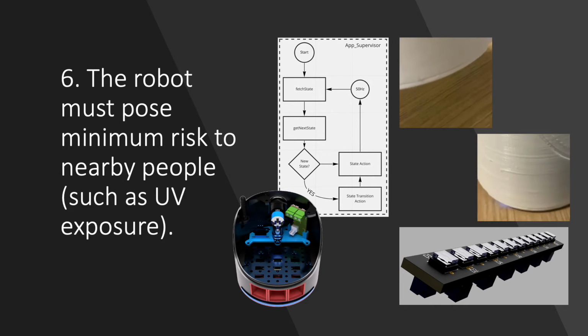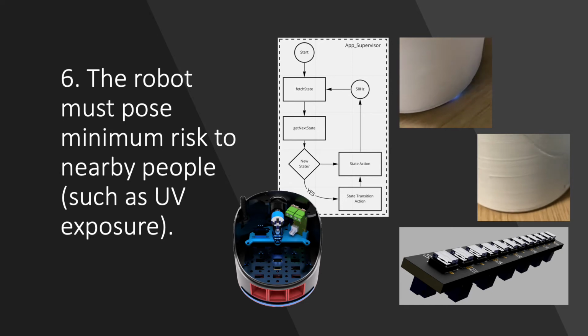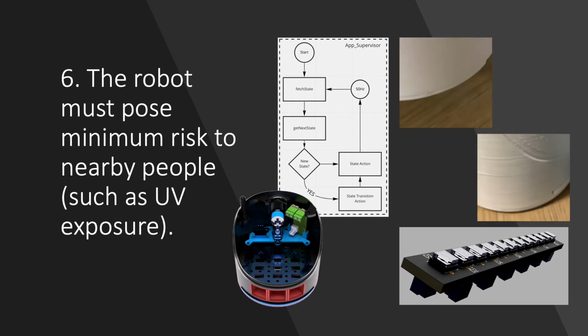Mechanically, the layout of the UV lights is designed to minimize UV leakage through the table reflections. The robot is elevated within 3 mm from table surfaces to increase the intensity of focused sanitization. We have a supervisor node and firmware to ensure the safe operation of the robot. As you can see, the UV is turned off whenever the robot is lifted or at the edge.